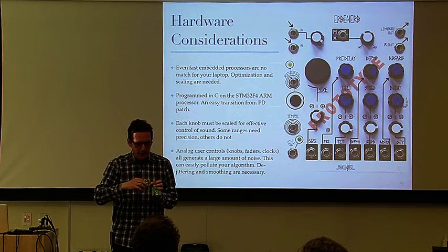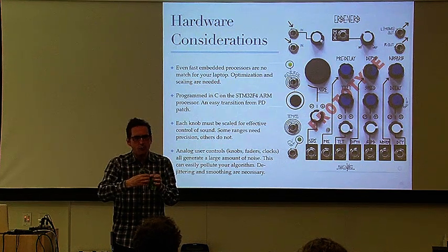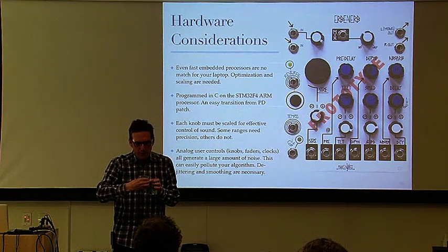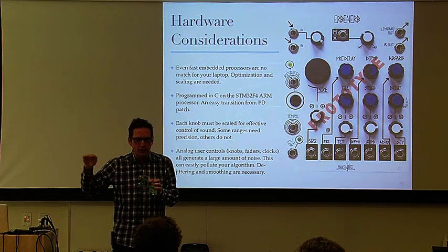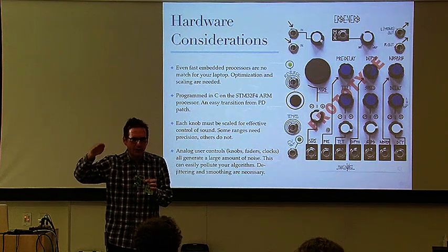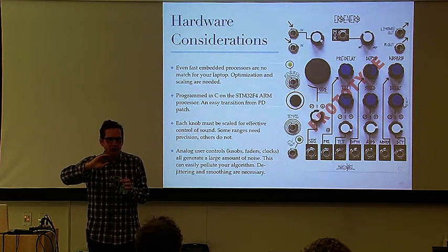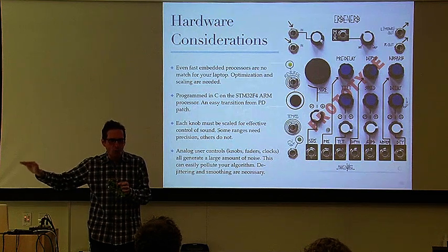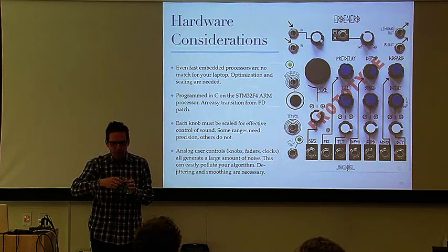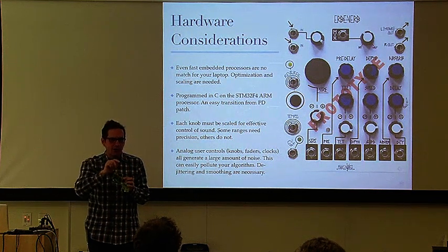And then finally, when you get a reading off the knob, say it goes from 0 to 1, you normalize it. But you might put that into an exponential parameter, and now you need to actually low pass your exponential parameter. You tune that so that when you turn the knob, you're not getting all sorts of Doppler. You want people to quickly change the speed and not have to go whoop, that kind of thing, which you might have heard on some delay lines, and you definitely hear on the Echophone. Echophone was done on a much cheaper processor.